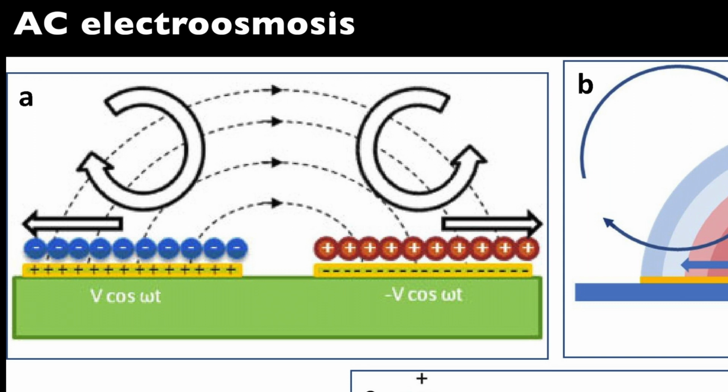non-uniform electric field. So the thickness of a double layer is inversely proportional to the electrolyte conductivity, meaning that for high electrical conductivity fluids, for example, most biological fluids, the thickness of a double layer is small, and therefore the resultant AC electroosmosis effect becomes weak. Thus, AC electroosmosis is more efficient if applied to liquids with low electric conductivities. Single electrodes as well as arrays of electrodes with different shapes and sizes in the milli-channels have been widely investigated